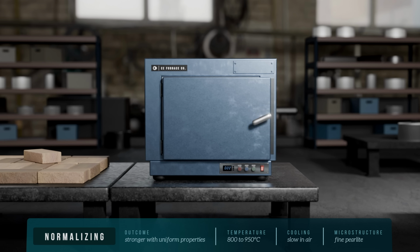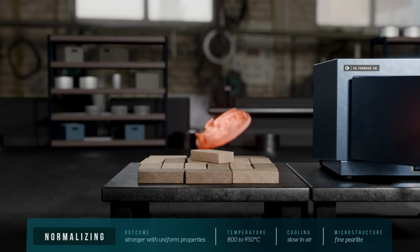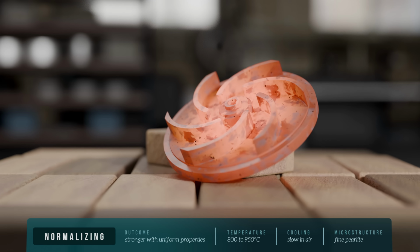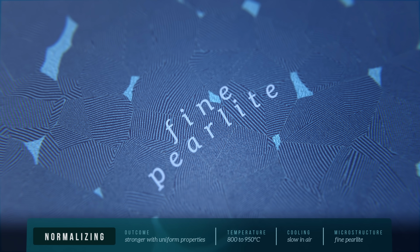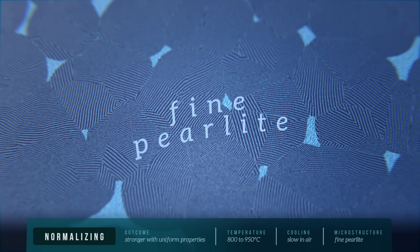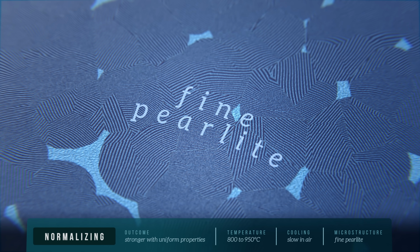Normalizing is similar to annealing. Both heat the steel into the austenite region, with normalizing using a slightly higher temperature. The main difference is the steel is cooled in air instead of slowly in the furnace. The higher temperature helps better eliminate irregular or patchy microstructure left over from previous processing steps like casting or rolling, and the faster cooling rate produces a fine pearlite structure that's stronger and harder than annealed steel, while still retaining useful ductility. The process normalizes the steel, resetting it to a uniform, fine microstructure with good strength and hardness.